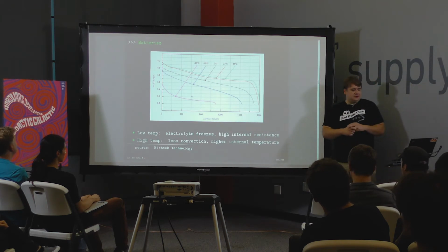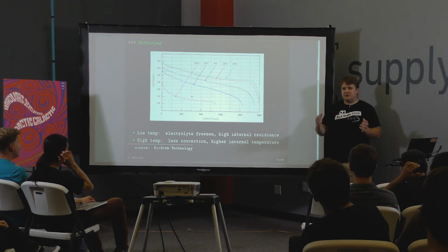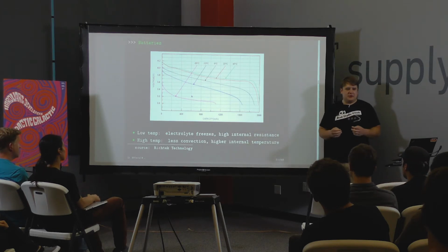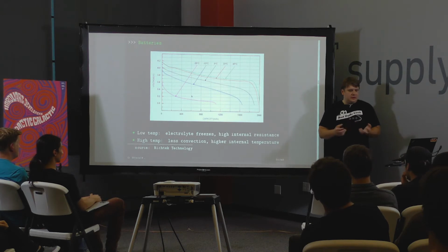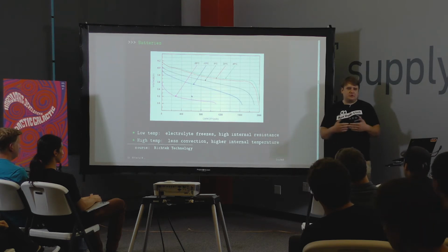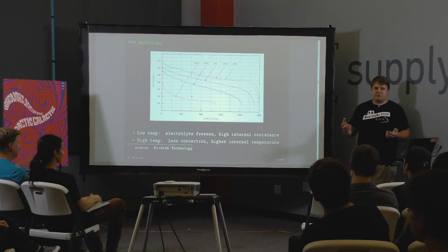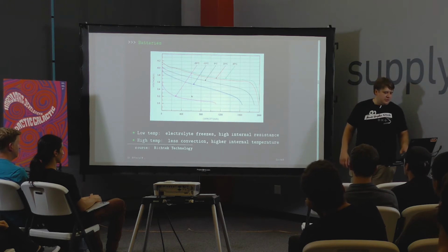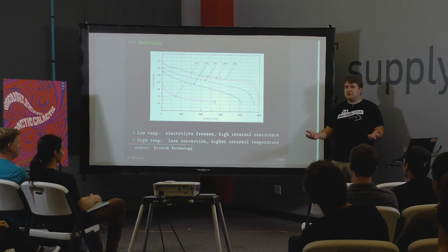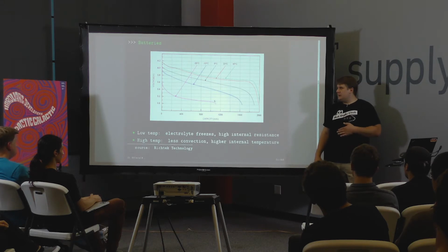And then batteries. If you want to do stuff in the air, you provide power. So you either have solar panels or you just put some batteries in, kiss it goodbye, good luck. And these are a lot of times lithium ion, things like that, they're not very tolerant to cold. What usually happens is when you have a battery, you have two dissimilar metals where you have electrodes and you have electrolyte in the center. That electrolyte is designed to convey ions. Once that freezes, pretty much you can't move anything. So your battery capacity goes down because you can't move charge. And you can very easily go down 10% capacity and permanently damage your battery if you let it get cold.